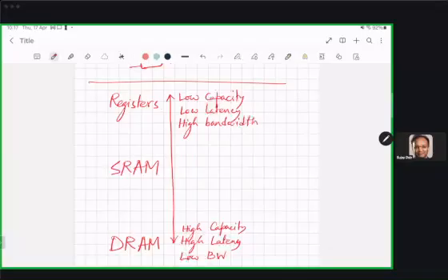So the processor will request data and it will give the address, saying get the data from this particular address. It will give a 32-bit number, a 32-bit address. You have to figure out where this address goes to, basically where it is located, and fetch the data. Now, since it is a 32-bit address, theoretically it can give anywhere from the 4 GB address space.